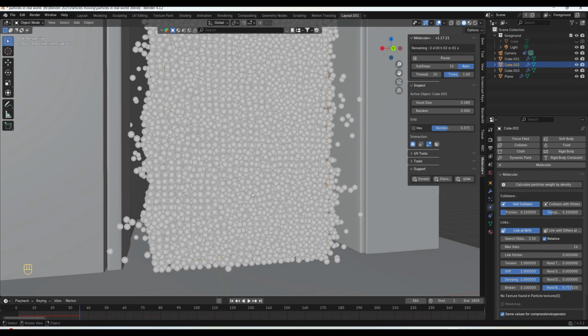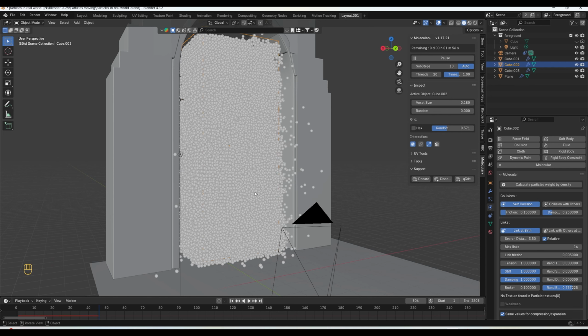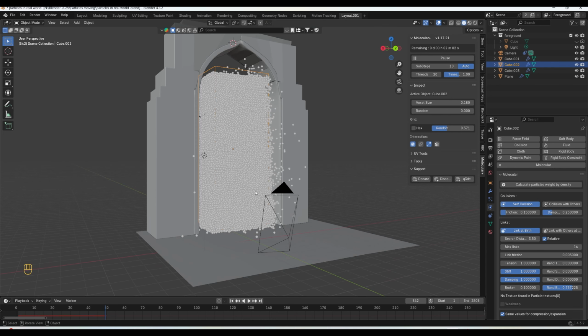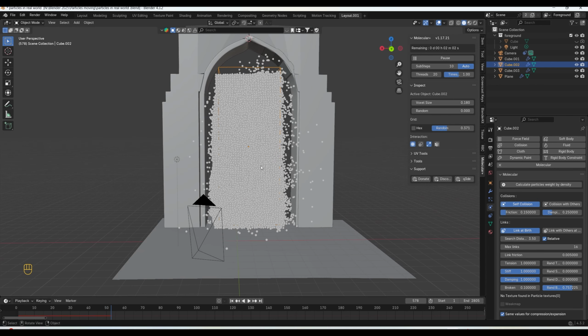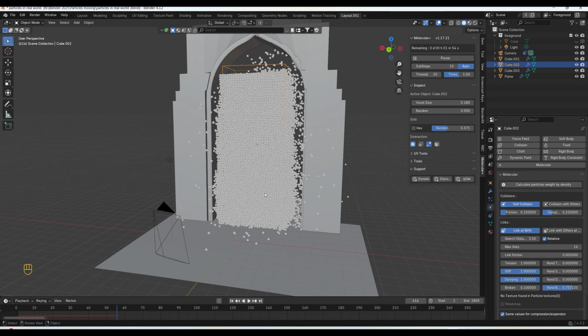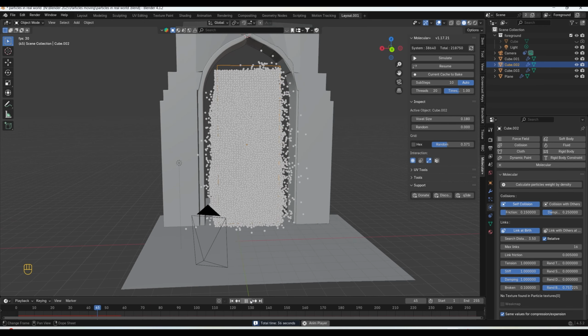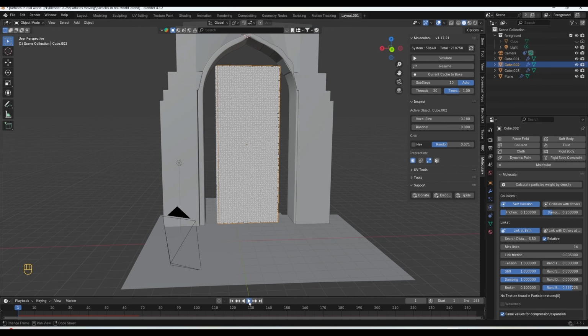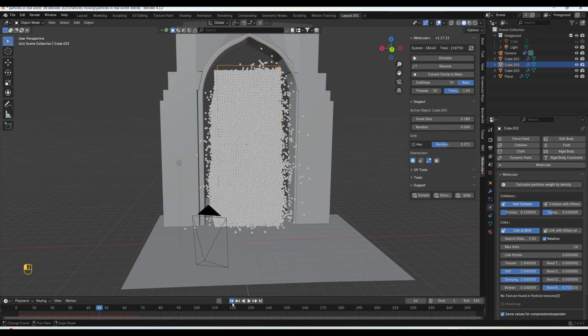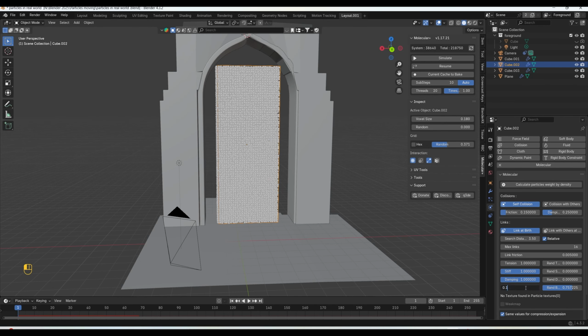So this is what I was thinking to do, because that way once we apply the forces, this particle will be able to break. So let me press ESC and let's check. So you can see, but these are too much, so I guess I have to reduce it. So make the broken point 1.5 and random broken point 5.